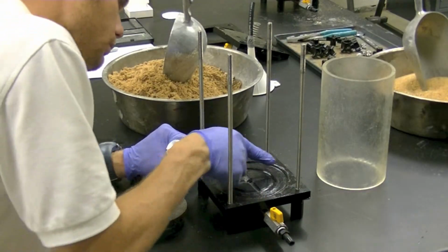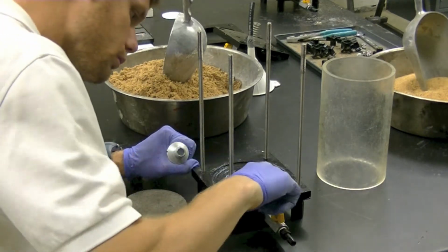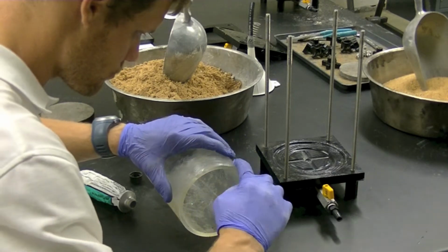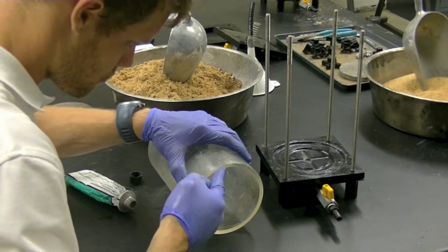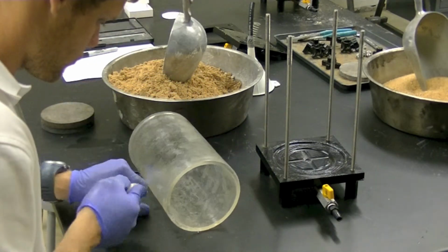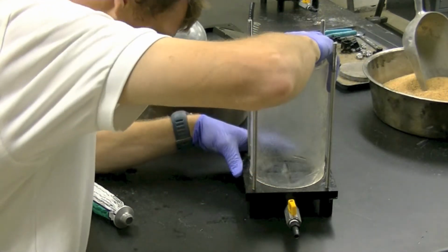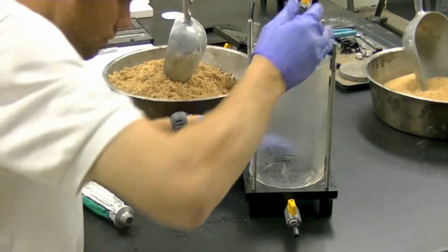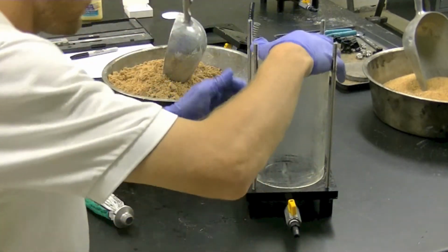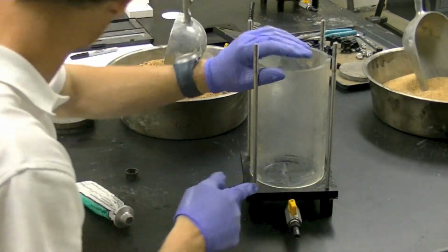The first and most crucial step in assembling the permeameter is greasing the gaskets. The vacuum seal grease prevents leaks from occurring during the test if applied properly. Grease all rubber gaskets on the bottom platen. Grease the outer diameter of the tube on the bottom end. Place the tube into the gasket and give the tube a slight turn so that the bottom end seats itself into the grease seal. Oftentimes applying a thin grease layer to the outside of the connection is necessary in preventing tiny leaks.